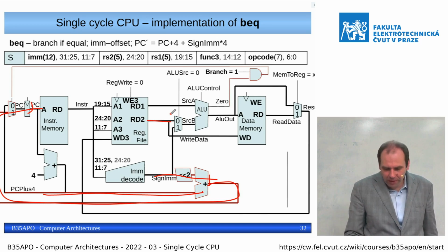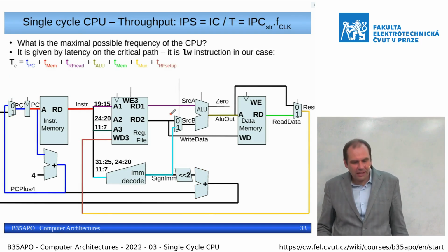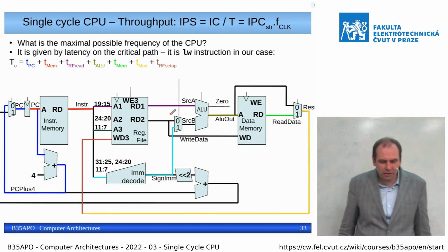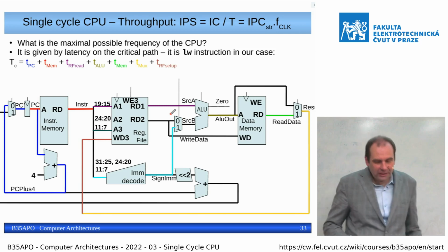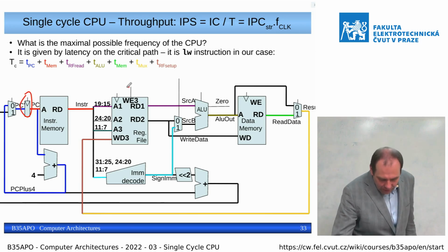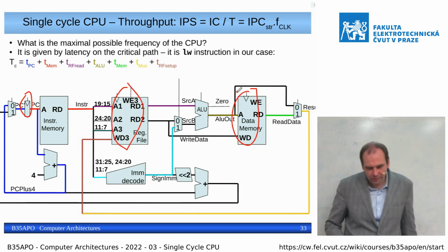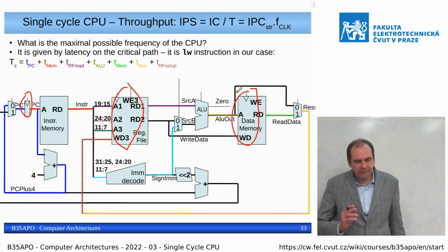But for 4 kilobytes it is enough. And we have a branch on equal. And at the end we have there a full processor data path which is single cycle, so only program counter, registers and memory are clocked. And we have there a problem.